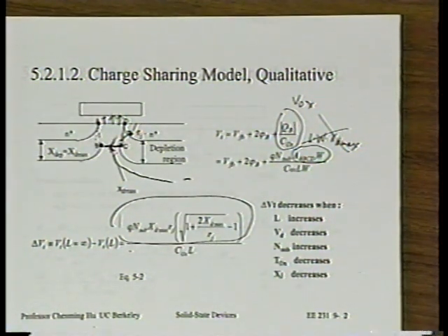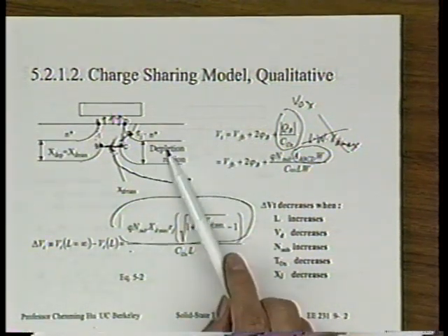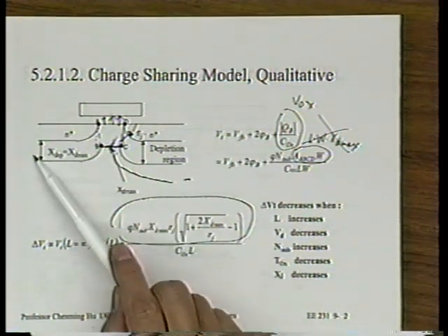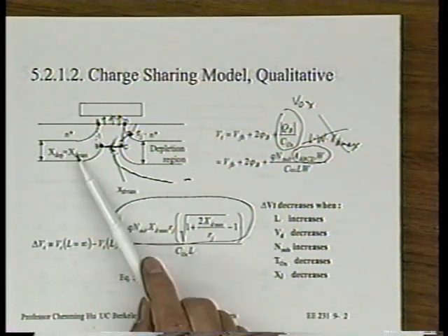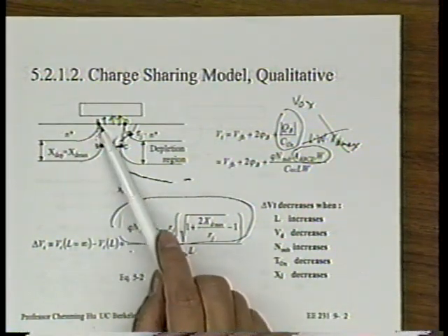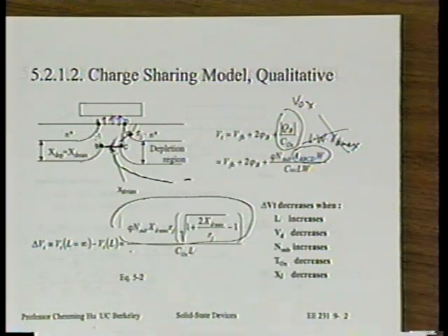How about when the doping concentration increases? When the doping concentration increases, all the depletion regions become thinner. Think of the extreme case of zero depletion width, zero depletion region length everywhere. Do you have any difference between the trapezoid and rectangle? So it makes sense. When doping concentration is stronger, the short channel effect is weaker. That's right. That's good.